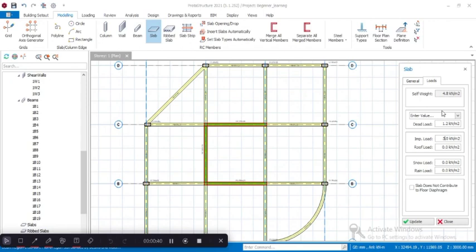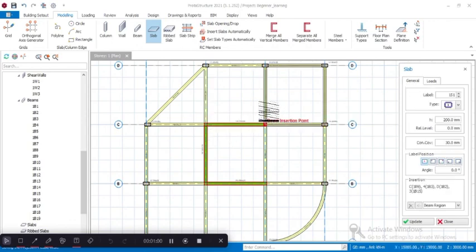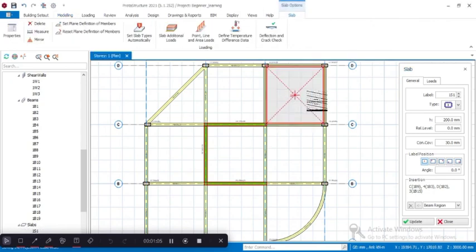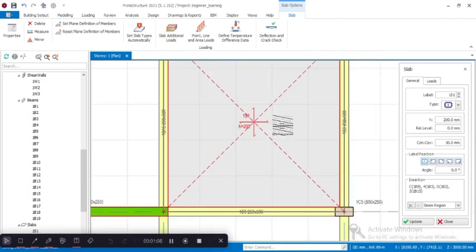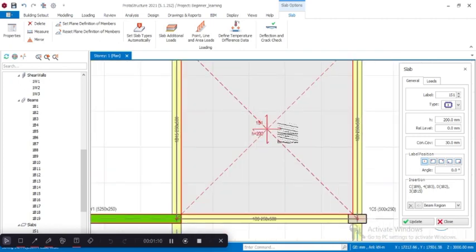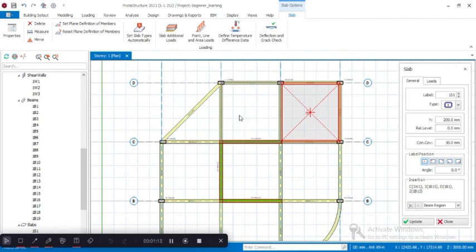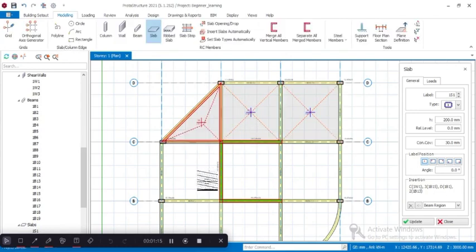Then you can insert more dead load because, if you see here, we have different values for different dead loads, for example for flat roof, room, terrace, balcony, and everything. If I click on any of these, it gives me the dead loads that are already automatically installed in the software. But this is what we're using now. So going back, we've been setting our loads, our slabs. So this will be our first slab. As you can see, it's there, and it's already automatically calculated as a two-way slab. So we're inserting 7 more slabs.